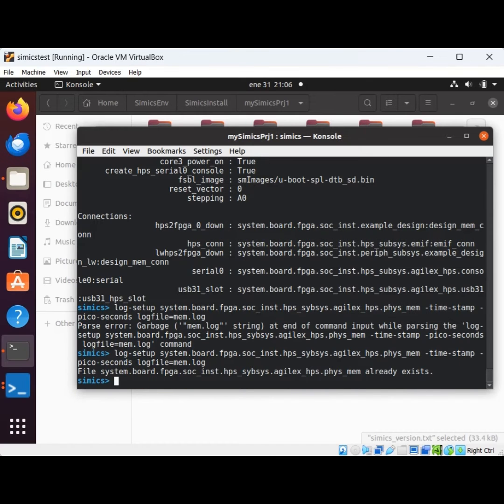We will now do a couple of examples for hardware inspection using the Intel Simics CLI. The target system has been deployed and the Intel Simics Simulator has started too. The system is not currently running. Notice the prompt has the word Simics instead of running, which is an indicator if the system has stopped or is up and running like any hardware.